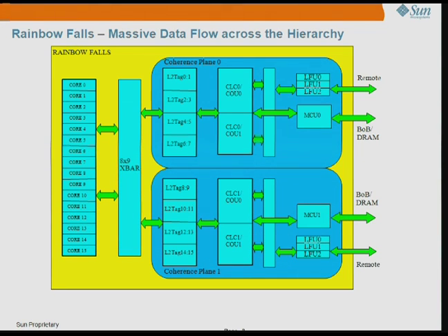So in ensuing pages, I'm going to focus on this area, which is the core crossbar L2 tag complex, and then this particular area, which is the coherency unit accompanied by its own ingress queuing crossbar and link frames along with coherency links which interface to remote nodes.